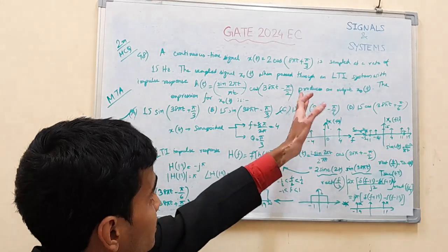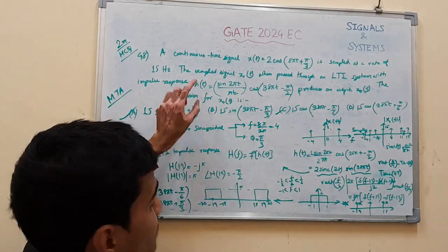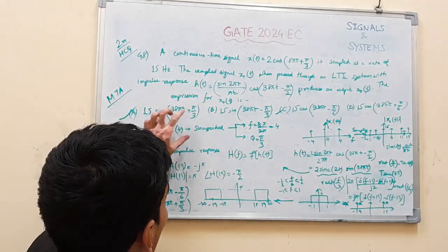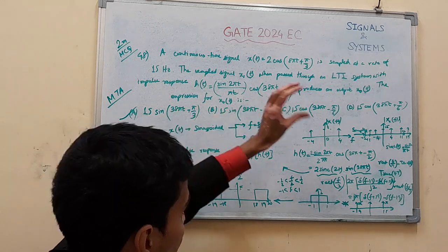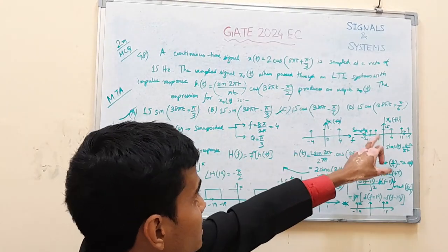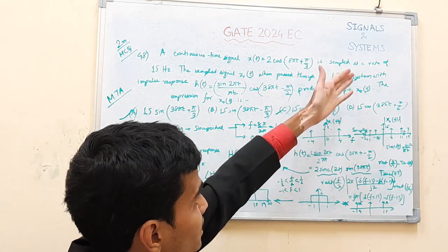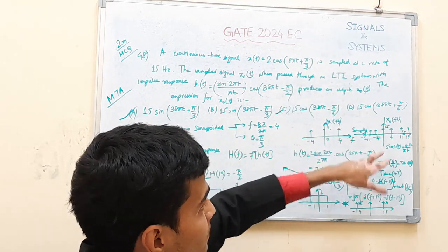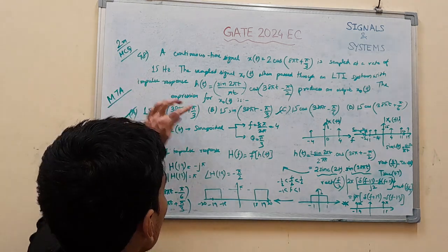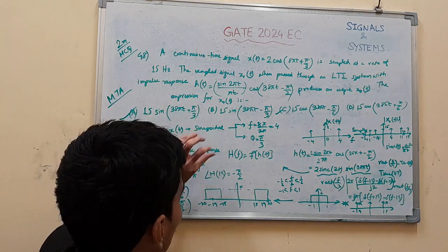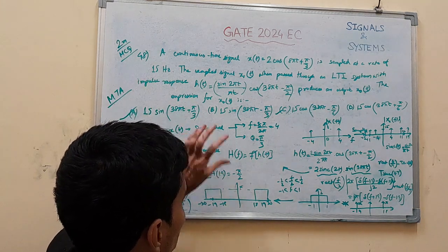And the steps are detailed. First, let's summarize. First, taking x(t), doing its frequency response analysis for its original version and then its sampled version. In the sampled version, the magnitude is multiplied by a factor of 50, the sampling frequency, and there will be infinite such samples. Next, we take the impulse response for frequency analysis in the frequency domain.